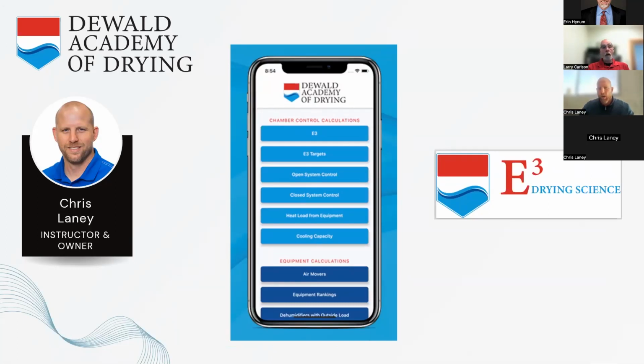Inside of our application, you have multiple different calculations. There's 19 different functions. You have E3. What E3 provides for us is the evaporation ability of the air. And we never had that single metric in our industry. Temperature doesn't give us that, relative humidity, grains, vapor pressure. None of those give us the evaporation ability of the air. And if we're using everything besides using heat panels, we're using the ambient conditions as a medium to evaporate water, and we need to be able to look at what that evaporation ability of the air is, and E3 provides that.